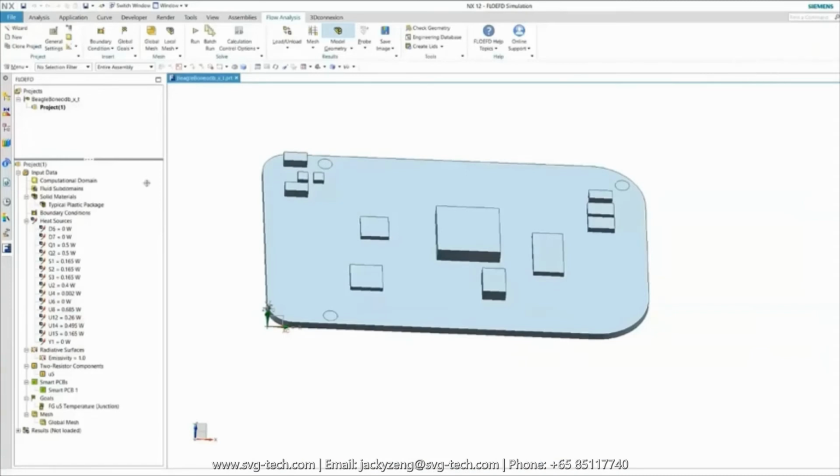We can access these components through a library, and we can build models in a way that CAD designers assemble CAD geometry. So this BeagleBone project is going to be set up using the package creator. Then I'm going to add this project to the top level assembly, and then FlowEFD will pull all of the conditions, material properties, etc.